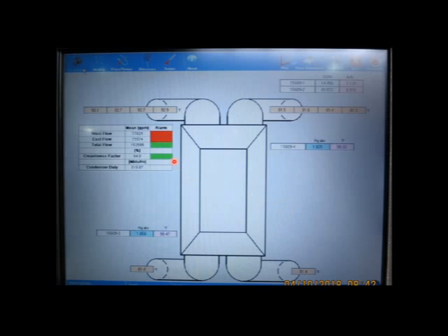We've got the flow rate, the inlet, the outlet temperature, so we can calculate duty and the cleanliness factor there. We've got the condenser pressures, two of them, one at the hot and cold end. We've got circulating water temperatures, inlet, and then four on the outlet here. That's a fairly decent spread in the data for the outlet temperature that we've located as far downstream as possible. And we have re-evac measuring air in-leakage, pump capacity, and some other values that we'll talk about.